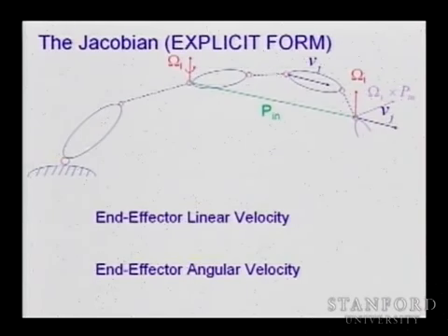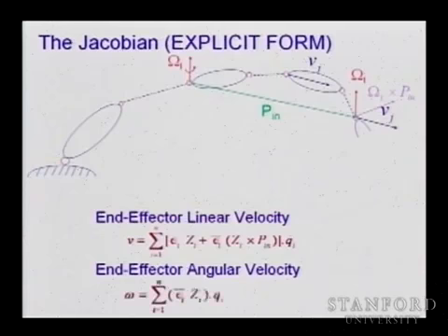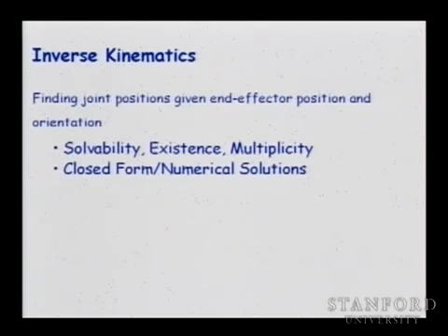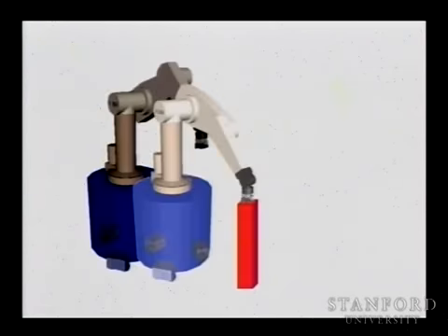the final resulting velocities. So we will also discuss inverse kinematics, although we are not going to use it extensively as it has been done in industrial robotics. We will examine inverse kinematics and look at the difficulties in terms of the multiplicity and existence of those solutions, and examine different techniques for finding those solutions. So again, the inverse kinematics is how I can find this configuration that corresponds to the desired end effector position